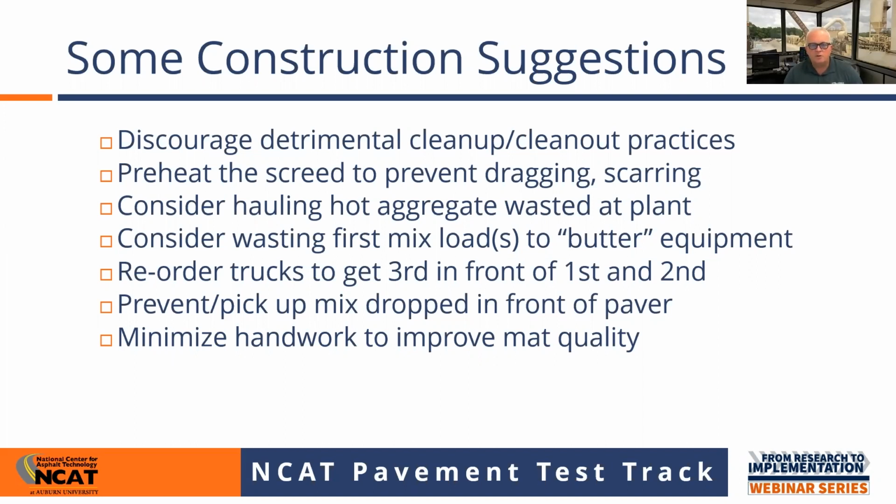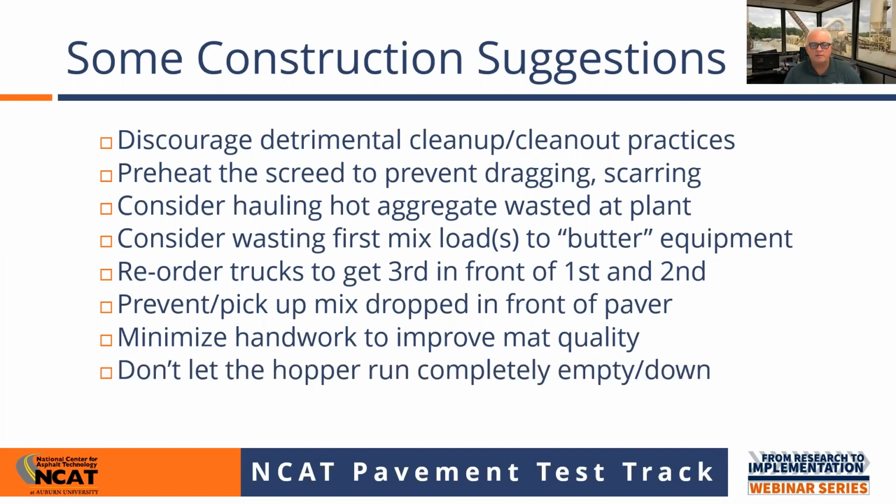If you do hand work, you're going to end up with some cold spots, and that material is going to be more prone potentially to raveling out in the short life of the mix, and then contributing to a really serious performance problem. So try to minimize the hand work, not just at startup, but all the way down the paving run that you're making.